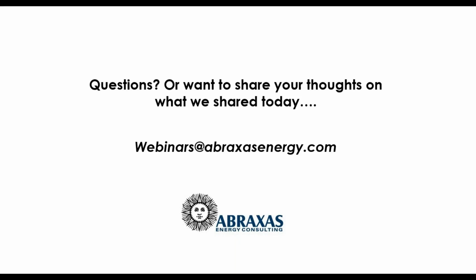There's a question also about, let's see, what if you don't get interval data from your utility? What can you do? And I'm going to give one answer, and I think Kevin will give a different one. But mine is, if you've got a big building, and I know Juan asked this, and Juan does have big buildings, you probably have a good BAS system, and I would think you can just add a point to your BAS. That would be an easy way to handle that.